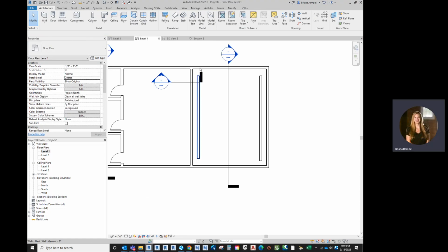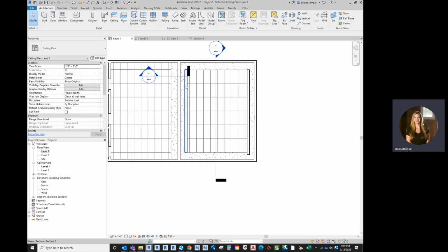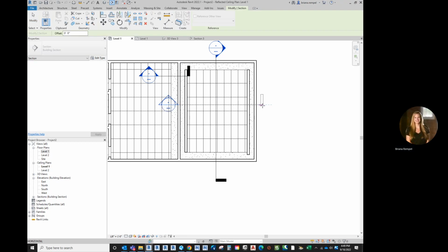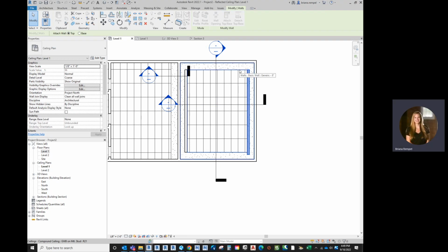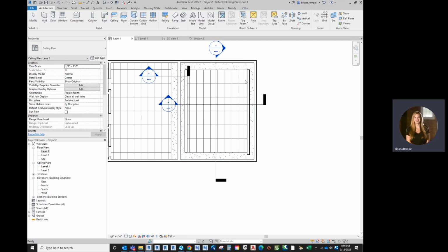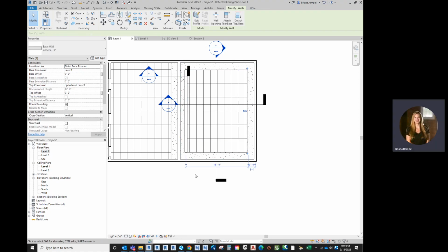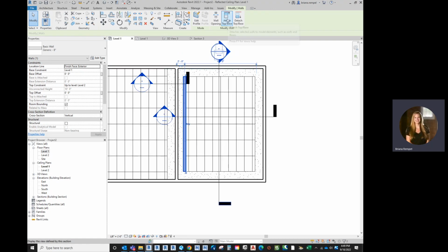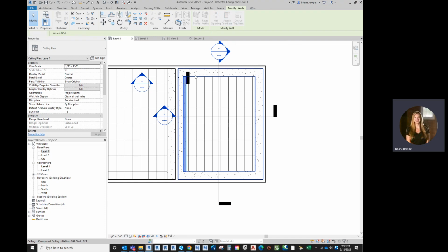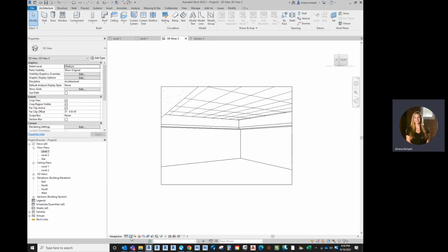You can see in the floor plan that these other 2 are still all the way down. You can see in the RCP, you can still see them here as well. So for that, would need a different section, cutting the other direction. See if it'll let me. Oh, it'll do it. You can do it 1 by 1. Nope. Oh, I just did the top again. 1 second. Attach base. Yeah, so you can do it in the RCP. You just have to do it 1 by 1, not all 4 like I did before. So you don't necessarily have to have the 2 sections, or you can do it in section if that's easier to visualize. And now I'll go back to that 3D view, and that's all cleaned up.